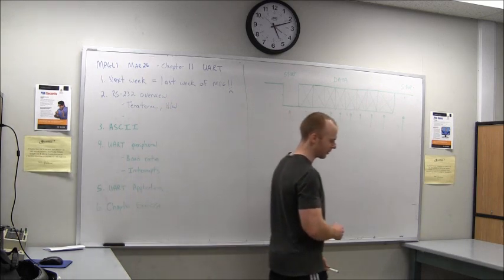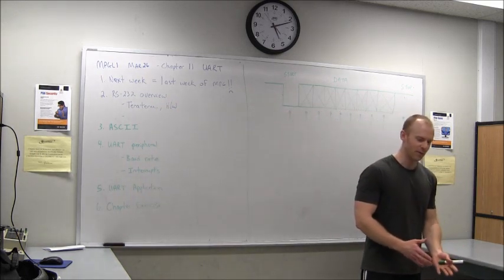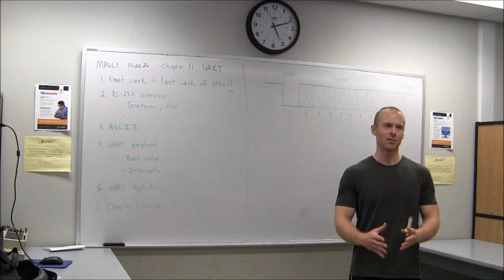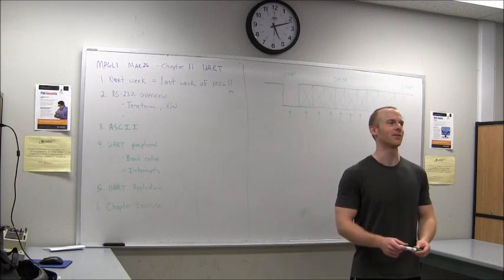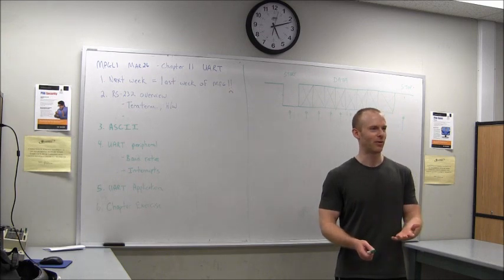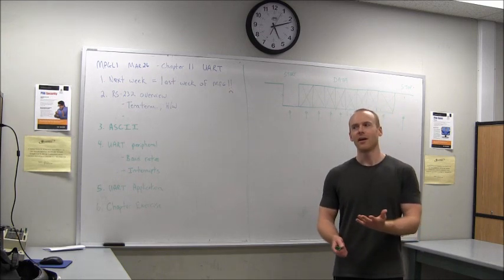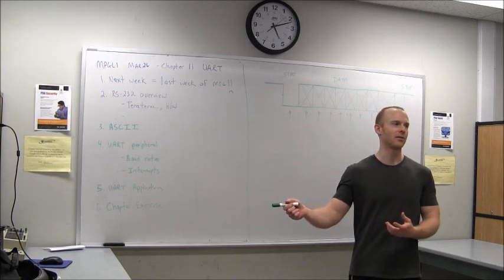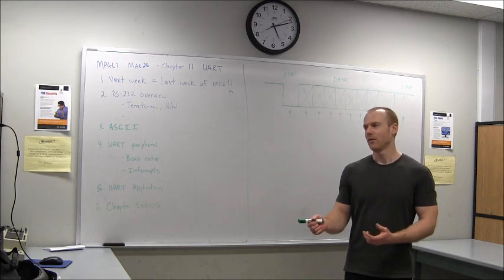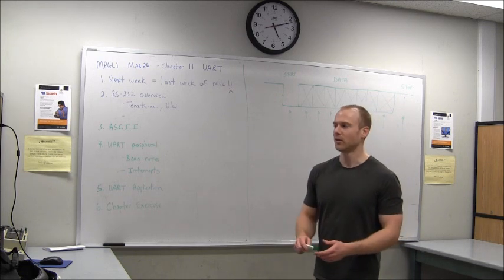So RS-232, you can almost interchange it with UART. UART stands for Universal Asynchronous Receiver Transmitter, which is usually what the peripheral in a microcontroller is called. The UART is what speaks to the computer. The computer uses the RS-232 protocol. Really the only difference is the hardware signaling.